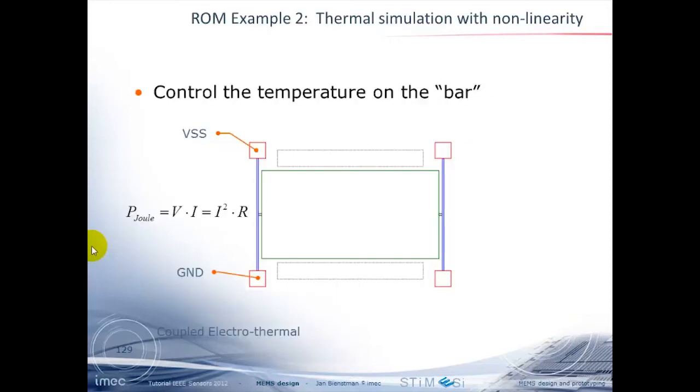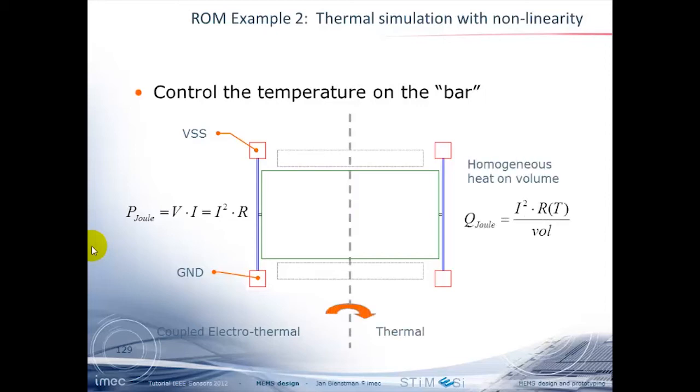Here's another example of this timing device. I'm going to go quickly over it because there was a nonlinear effect in it. So actually, if I have, let's say, a current of 1 amp through it and I see a response, doubling the current would make the power 4 times larger. But if I include that in my reduced order modeling, my reduced order model will just assume that the power is doubled. But you can split out the nonlinear effect, and in this case we just applied a certain continuous Joule heating to the structure.